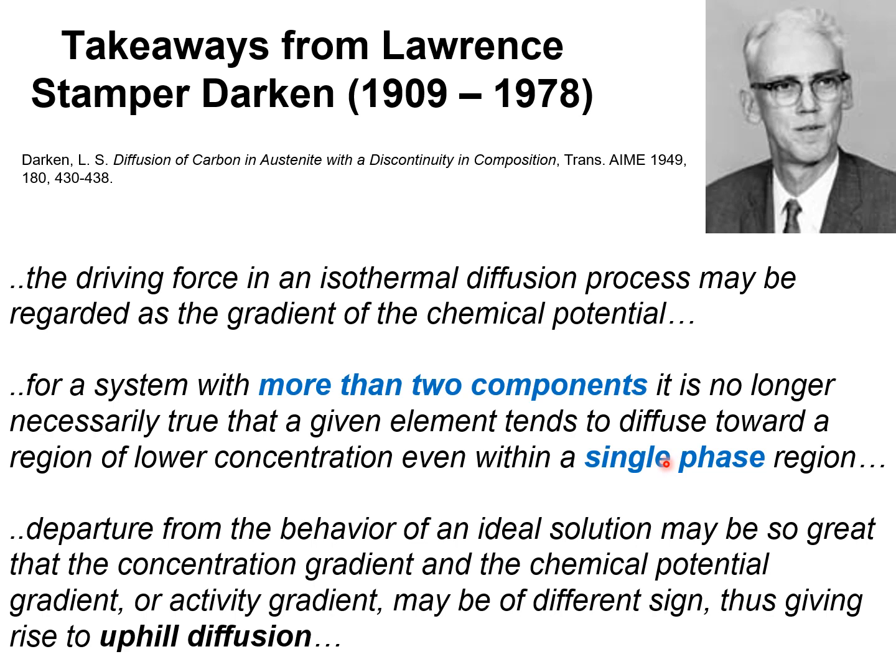The word single phase is quite important, as we shall see later. The departure from the behavior of an ideal solution may be so great that the concentration gradient and the chemical potential gradient or activity gradient may be of different sign, thus giving rise to uphill diffusion.